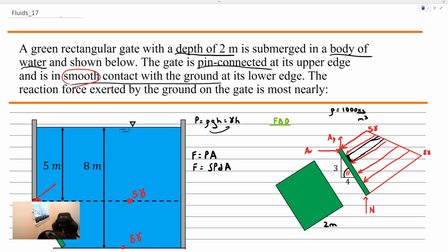Once we raise it up to the pressure, we geometrically get an area shown on the screen, and once we expand it through the depth, we get a volume. After we add up all of these volumes, we're able to compute a force. The takeaway is that geometrically, when you find this volume under the pressure distribution, what you're computing is a force.